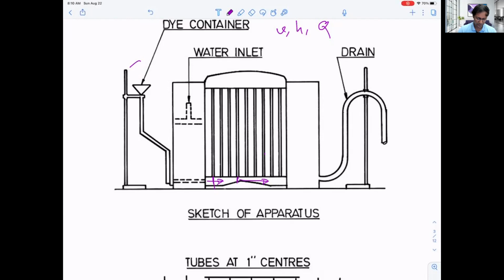So in this tube, water will be here. Since the section is decreasing, the flow velocity will increase. However, the P by gamma will decrease. And again, as the section increases, it will be like this. So if we plot, it will be like this. We'll see the plot and check if it is like this.